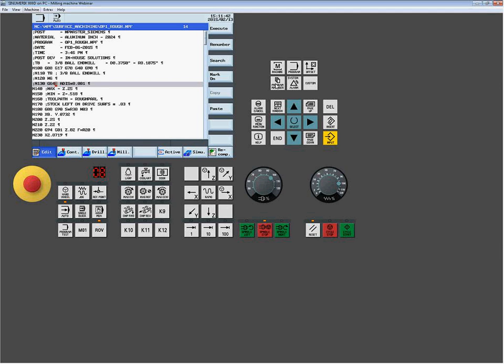Whether I want the spindle and feeds is really up to you. I'm not that concerned because I'm passing them through with R variables. But you don't want operators to go into the subs to make any editing changes. The area they should go into, if any, would certainly be the main program file. I've commented out these lines. If this was a real part that I was going to do in production, I would just delete them. No need to see this kind of stuff.